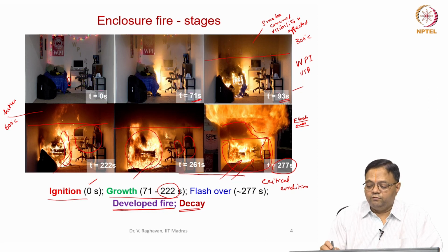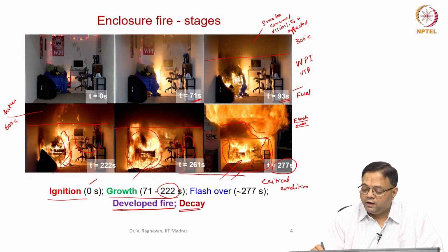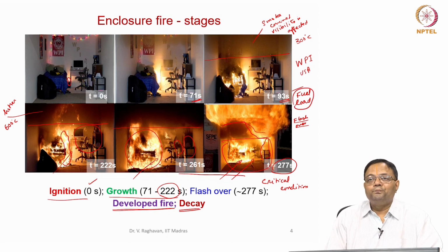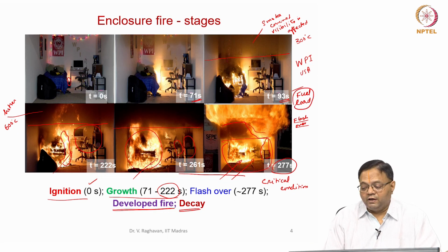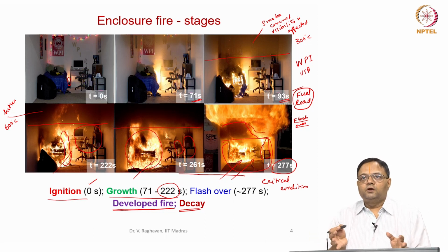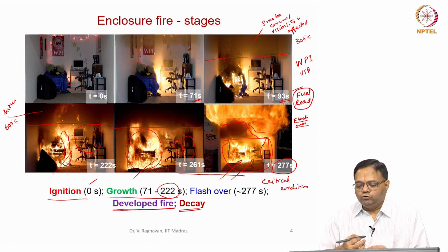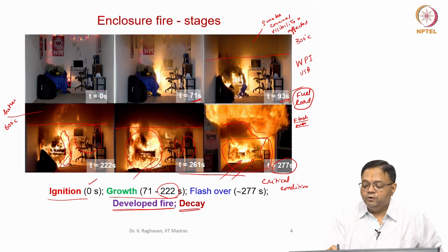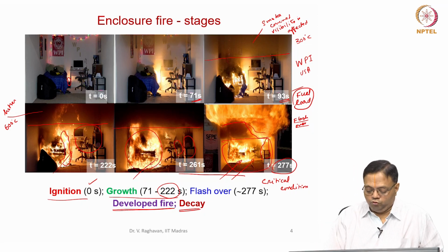What are all the flammable fuel loads? What are all the flammable materials inside the room? And when I say flammability of this material, including the ignition, fire spread characteristics, etc., then how much opening is there for air to enter? Because for burning so many commodities, not enough air can come in at the required rate. That is the reason why the fire is seen outside the enclosure also.